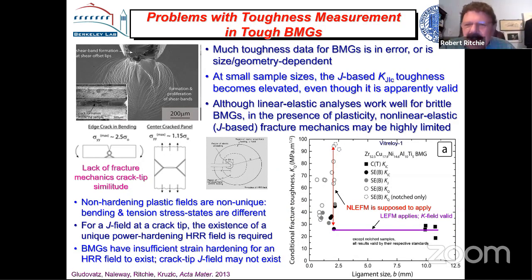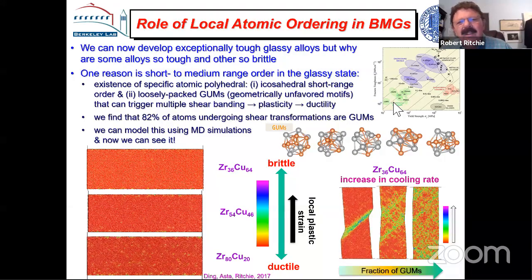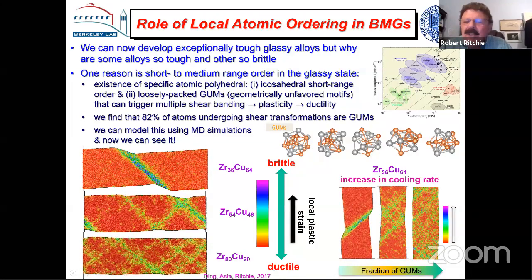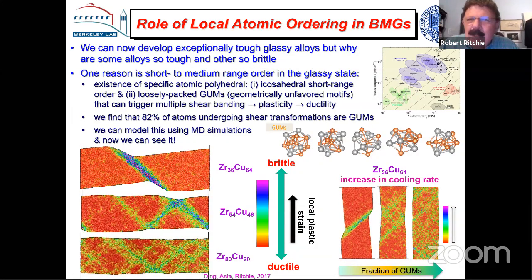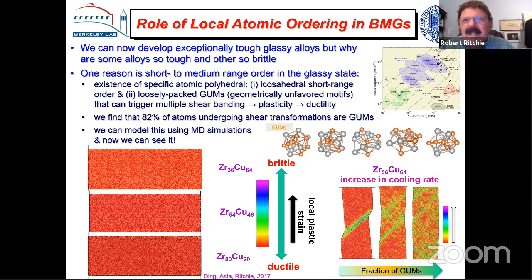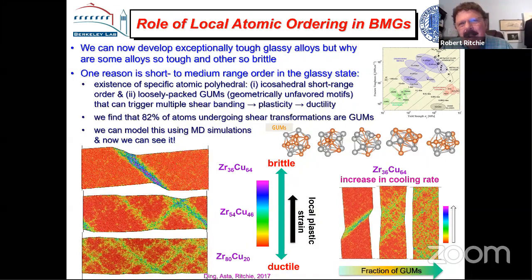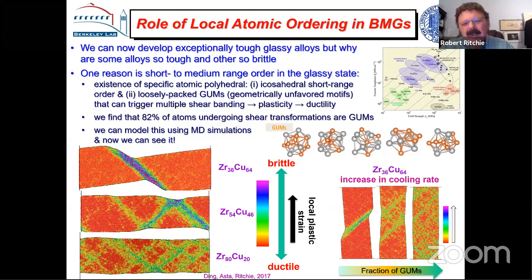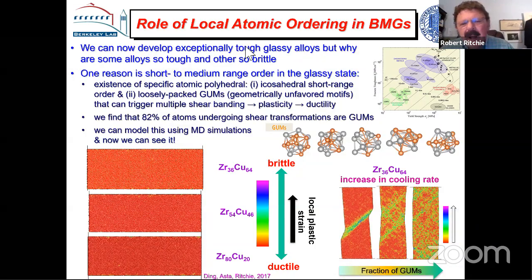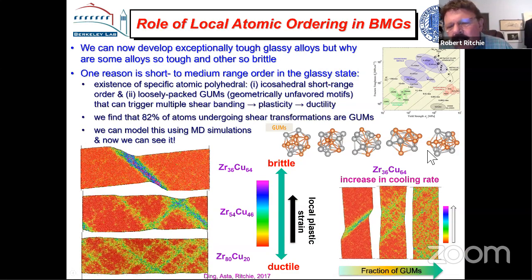But there's another factor which is a little bit even more interesting. And that is the fact that these glasses, they're amorphous, but what does amorphous mean? Now, certain people talk about that the amorphous glasses, like Lindsay Greer, have a nanostructure. And what we've done with this, and this is something that came out of Evan Ma's work with Jun Ding, who became my postdoc, with Mark Astor here, is that in the amorphous state, there is short range order.